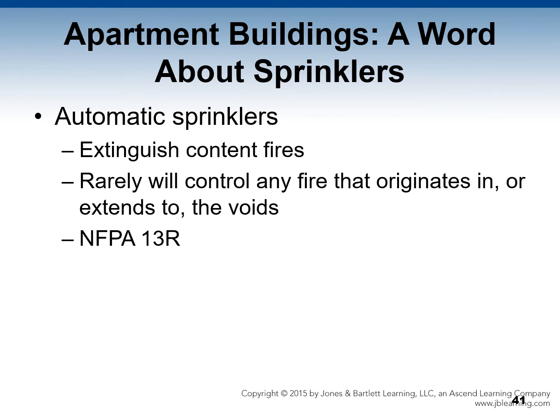Now let's have a word about sprinklers. We're still talking about apartment buildings here. Automatic sprinklers extinguish content fires, but will rarely control any fire that originates in or extends to the voids. NFPA Standard 13R, which is the standard for installation of sprinkler systems in low-rise residential occupancies, is a tremendous safety feature. Unfortunately, some states do not require enforcement of this, and landlords do not always comply with it.